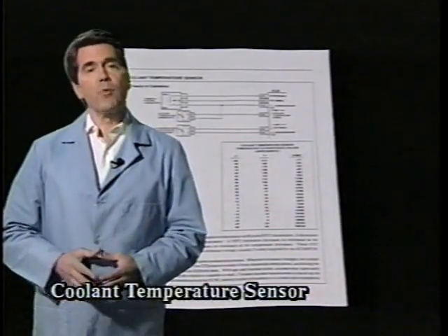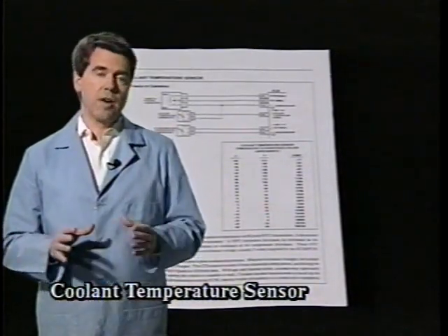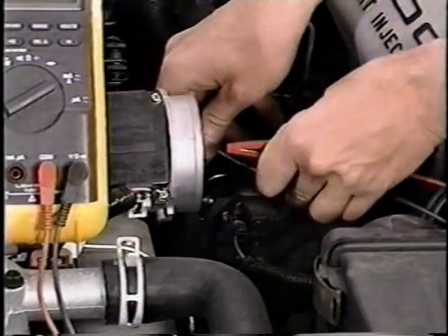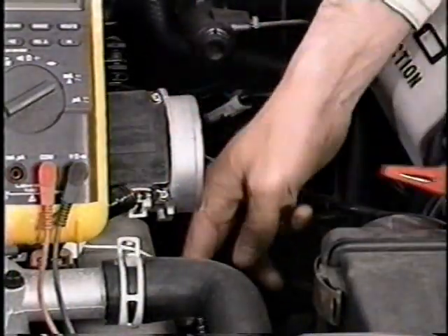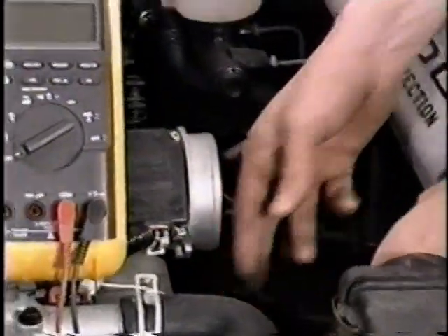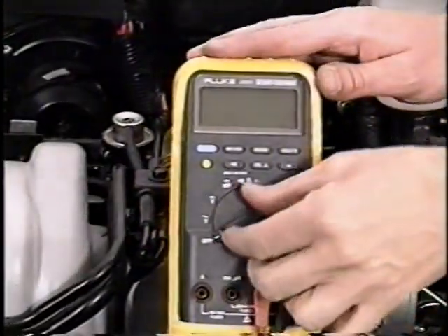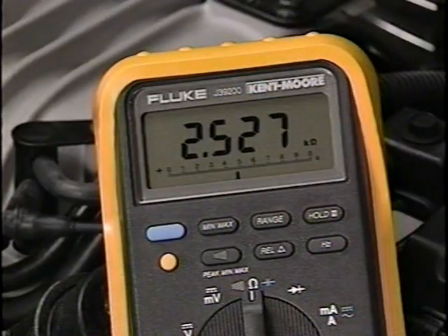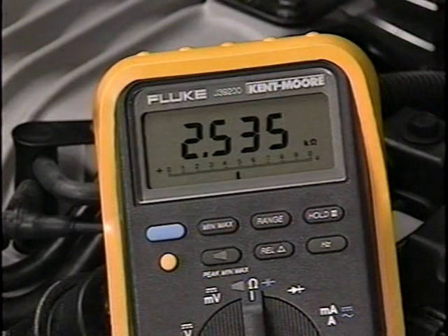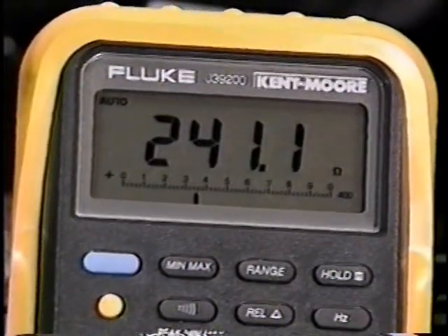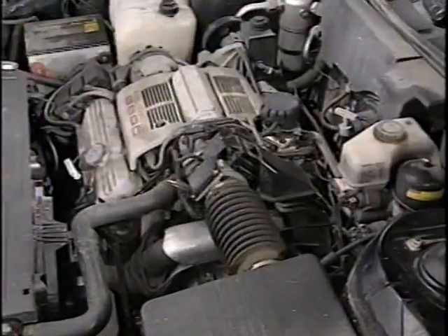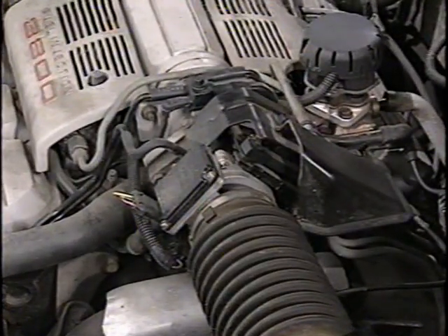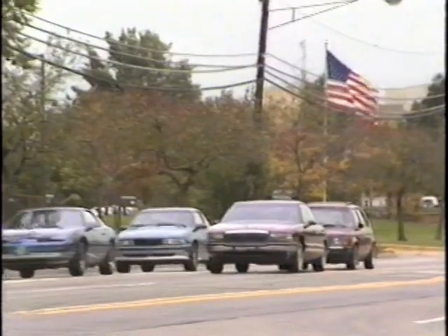If you take, for example, the coolant temperature, the section starts with a typical wiring schematic. In the description of coolant temperature sensor operation, it's explained that the coolant temperature sensor is a negative temperature coefficient thermistor. In other words, the coolant temperature sensor has high resistance at low temperature and low resistance at high temperature. With age and thermal stress, a sensor may fail during engine warm-up, causing the vehicle to stumble or stall while